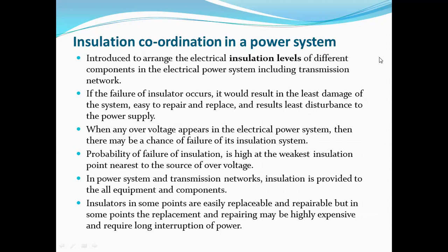So we use insulators for some equipment, or for some lines, but not for all. But we can protect if we use insulation of a higher value than the rated value, then we can surely protect that equipment, or the line also. So how that works will be seen in this point, that is insulation coordination in power system.